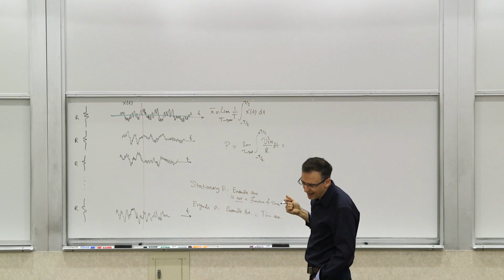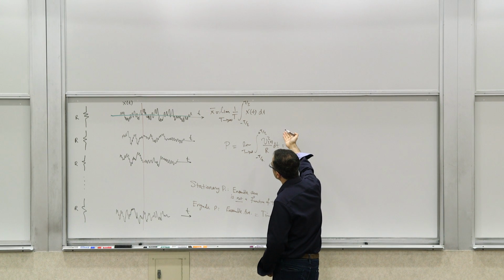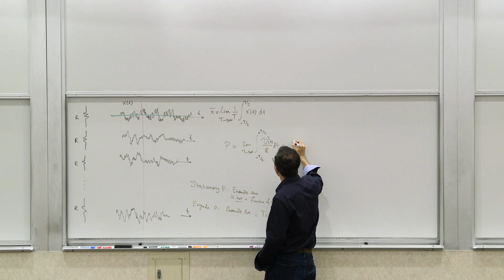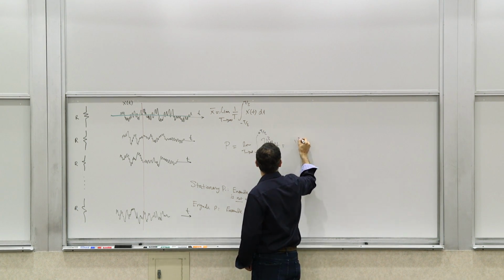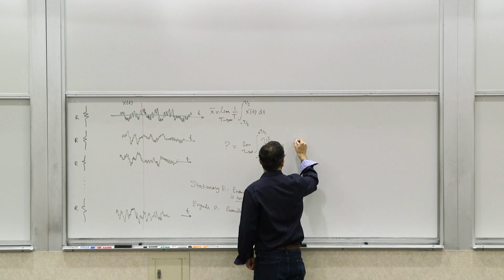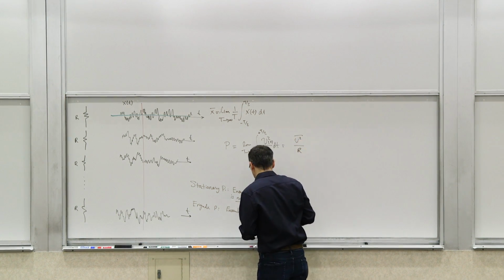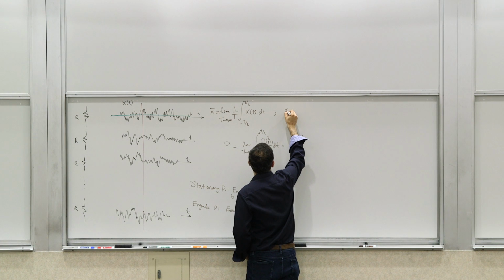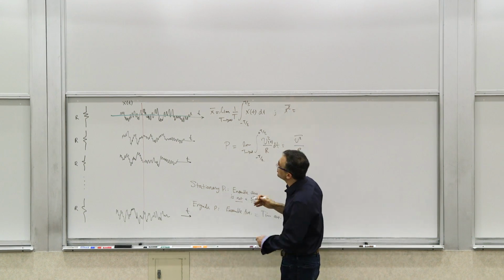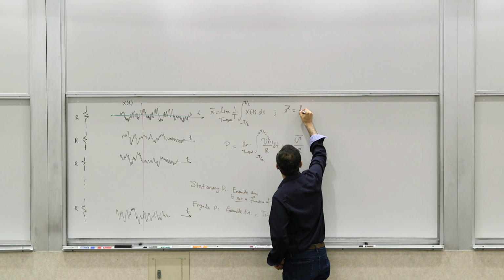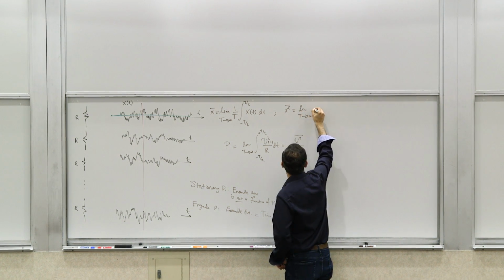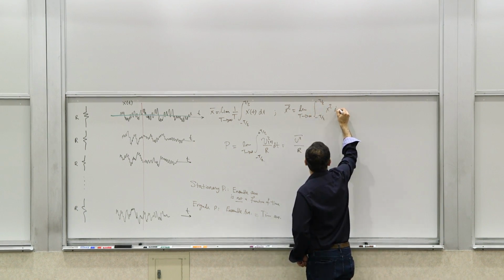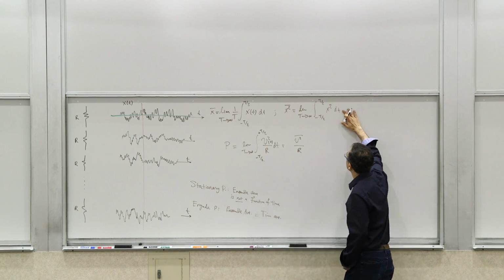Now, in general, if X is some sort of voltage or current, we show it as a signal. So if, for example, X was a voltage, then you could write this as the statistical average of X squared, or V squared over R. So what this means is that you can define these higher order moments. If you had a signal X, you could define similarly its quote unquote power as the average of its square. So this would be its power.